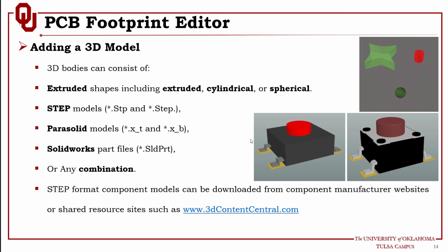Now, adding a 3D model to the footprint in Altium Designer, it's not only restricted to the STEP file format. Actually, Altium Designer accepts STEP models like STP or STEP, also Parasolid models, X_T and X_B, and SolidWorks part files, also you can use them. But STEP is always preferred, and also you can use a combination of these. You can import multiple 3D models to construct a specific shape